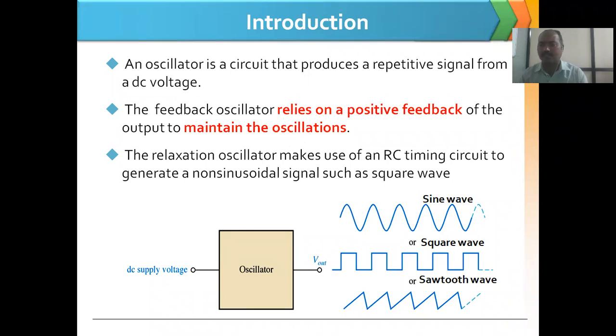Okay, now see, negative feedback indicates that whatever input is applied, the opposite is applied again. Means if we have applied a sine wave as the input, consider the output is coming as a cos wave and it is again applied. So what happens, due to the negative feedback, there is a reduction in gain, right? Reduction in gain. Now see, we just talk related to the amplifier.